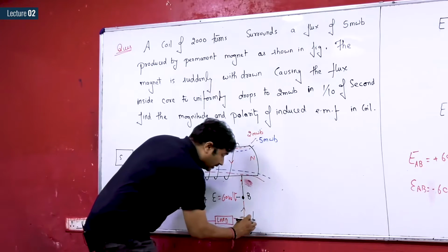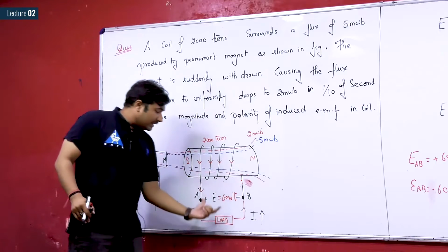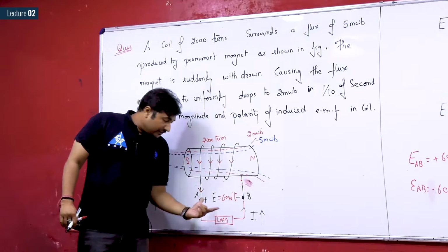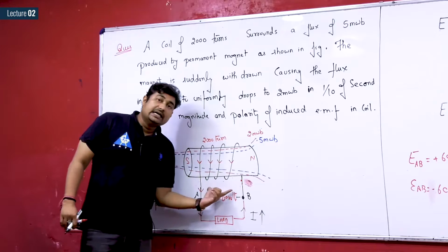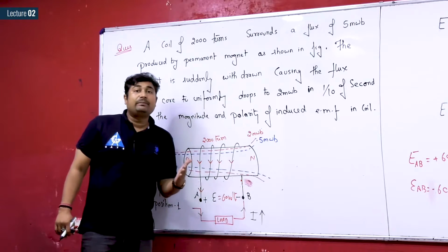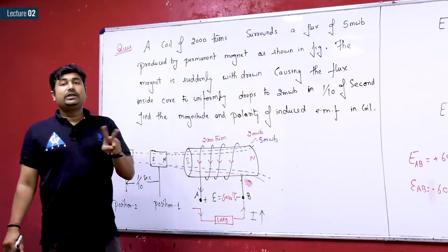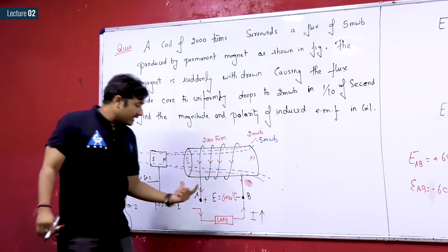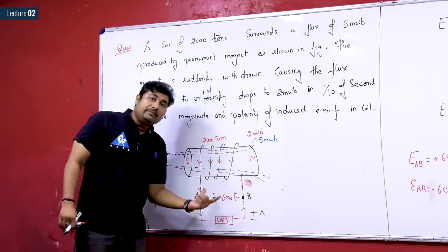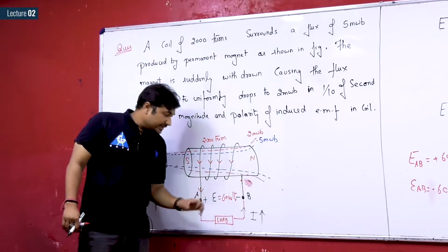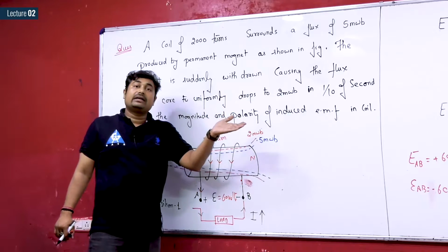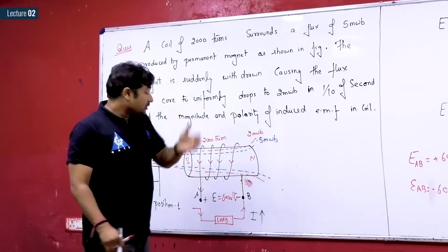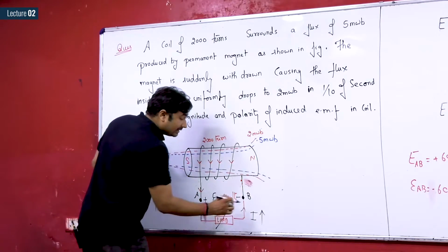In case I increase the load, it means now I am going to connect the load in parallel, because electrical loads are always connected in parallel. If I connect the load in parallel for the same voltage, the parallel impedance will go down. If two equal impedances are connected in parallel, then the equivalent impedance will become Z by 2. For the same voltage source, if impedance goes down, current increases. So whenever in electrical circuits we say that load is increasing, it means the current is increasing.